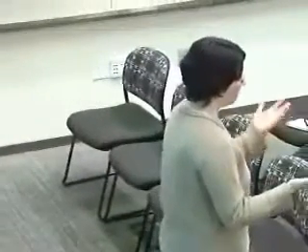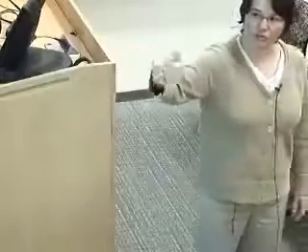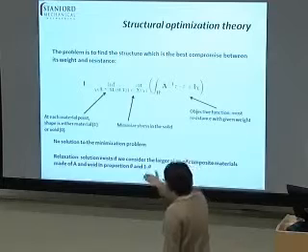And if you want to solve that mathematically, find the optimal shape of your structure, well, you can't, because there is no solution. Why isn't there any solution? Well, because your problem is too restrictive in a sense. You have a black and white solution there. And you can show rigorously that you can transform this problem into one that has a solution. And the process to do that is called relaxation.